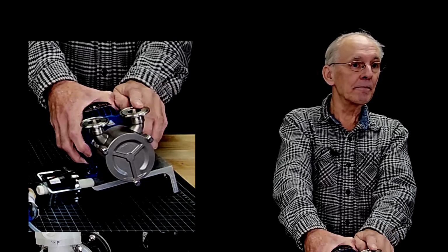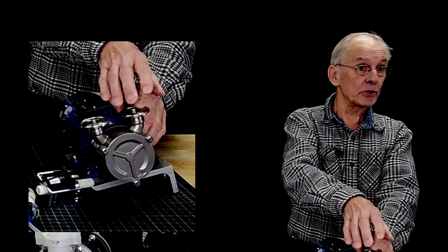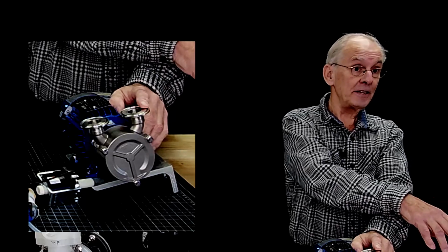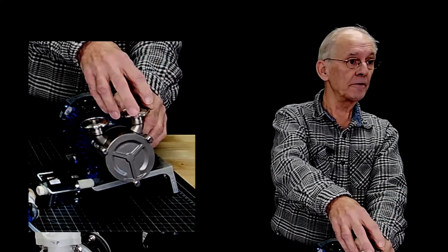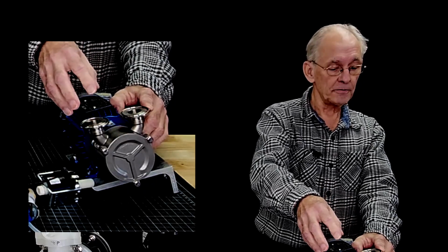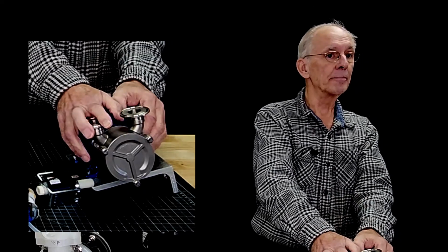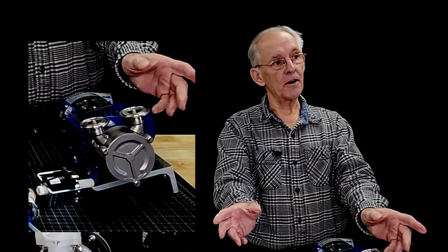Because with this pump, I can pull a suction from 15 feet down and pull permeate off of the membrane, and then every so often simply reverse the pump and backwash the membranes. And there are no valves involved.